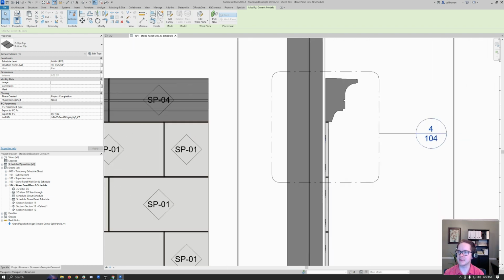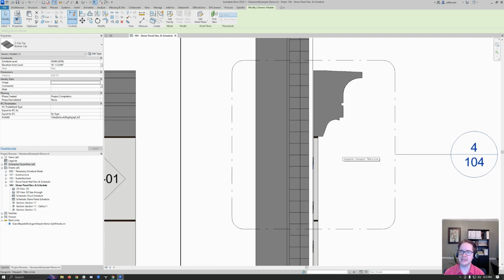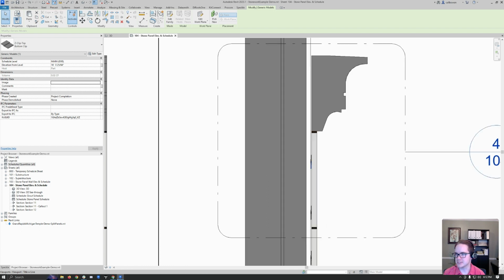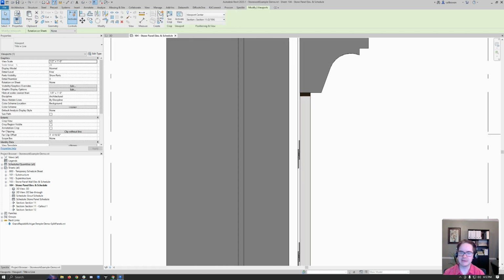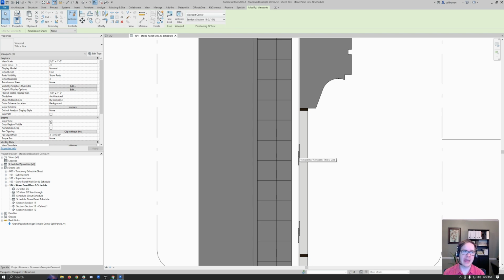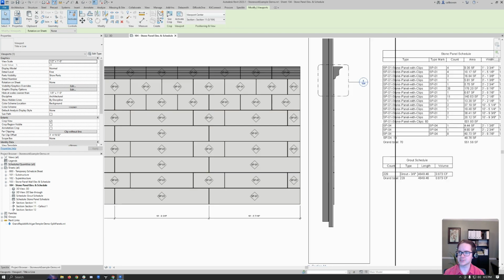And what's exciting about this is there are no detail elements here. What I mean to say is that often when you create a detail in Revit, you kind of fake the funk, so to speak, and you draw some lines and some hatch patterns. Nothing that you're seeing here is a detail line. Actually, I didn't even put any dimensions here. This is au naturel. These are separate elements within Revit. So that's really exciting. And let's go take a look at our 3D section views down here.